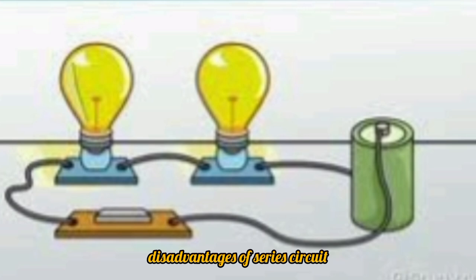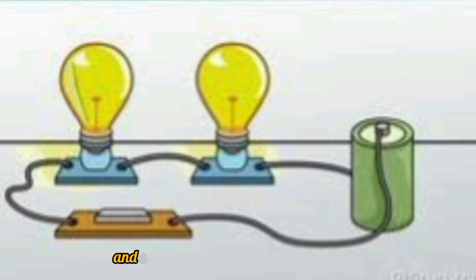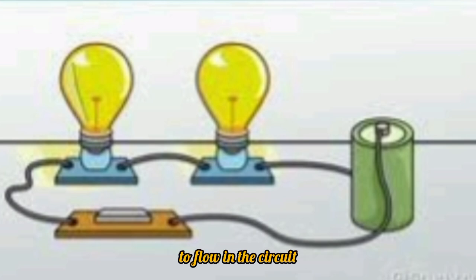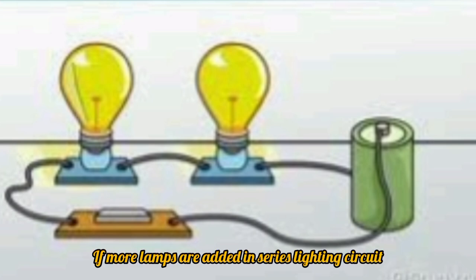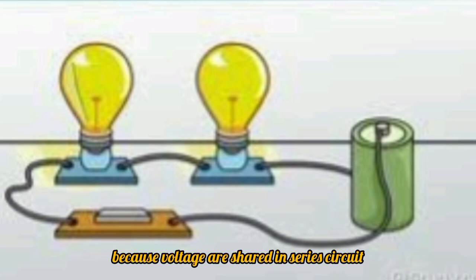Disadvantages of series circuit: a break in the wire, or failure or removal of any single lamp, will break the circuit and cause all of the others to stop working, as there is only one single path for current to flow in the circuit. If more lamps are added in a series lighting circuit, they will all be reduced in brightness because voltage is shared in a series circuit.